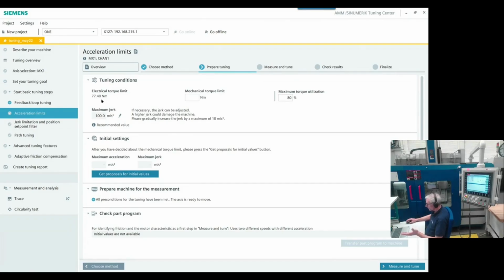Normally, if you have that situation, you should limit the torque in the torque limit of the drive. But if this has not happened yet, you can tell us, oh no, you can't use that, you can only use 50 or whatever. In my case, I'm safe. I can use whatever higher number to make sure that the electrical limit is our actual limitation.